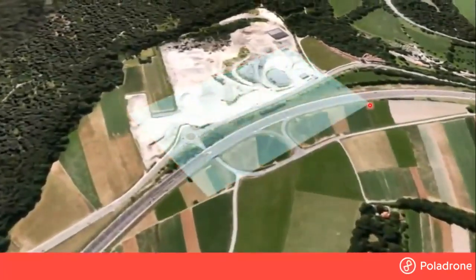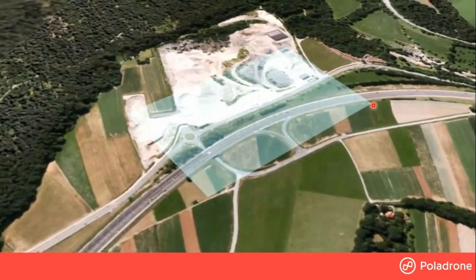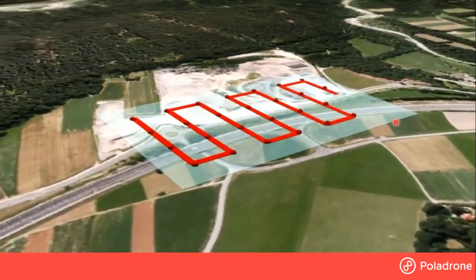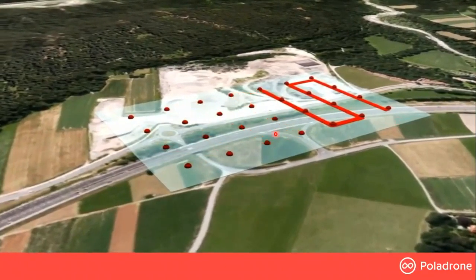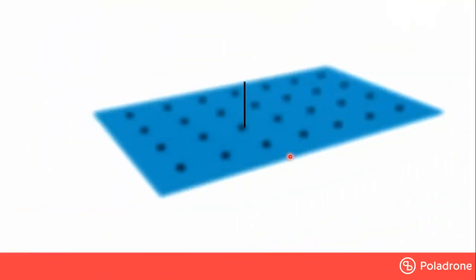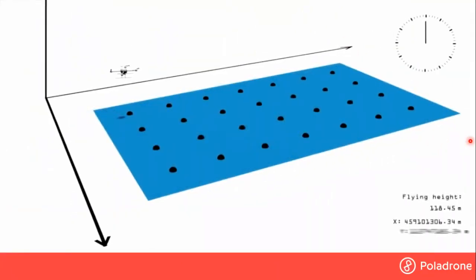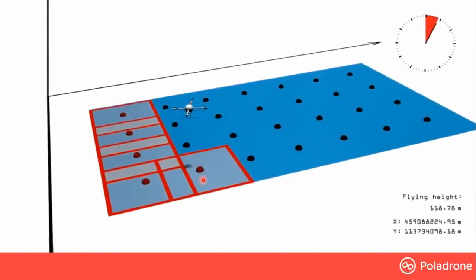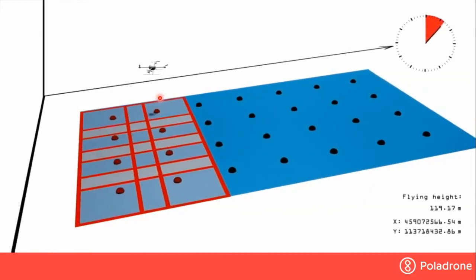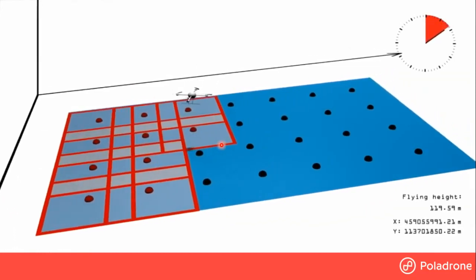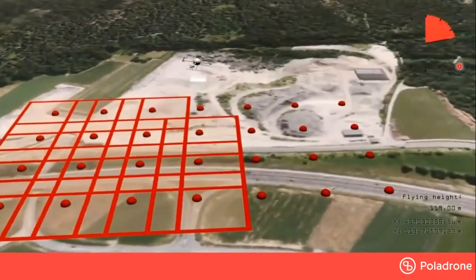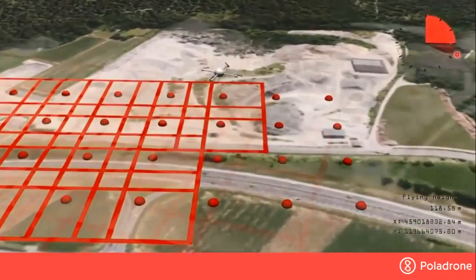So first of all, say we would like to fly in this area. Then what the drone is going to do is we use the operational software to create a waypoint. This is a path that the drone is going to follow. And as the drone flies, at each of these dots the drone takes a photo. In the top right, you'll see the time estimate for the whole project to complete is around 20 minutes plus.